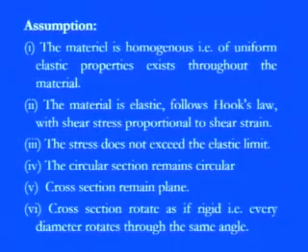So these two are the biggest assumptions: the material is homogeneous and is within the elastic deformation. Then there are more assumptions, like the stress must not exceed the elastic limit, because once it goes into plastic deformation, a permanent set of deformation exists in the material. Even if you release the load, the circular shaft has a permanent deformation, and if you apply more load, it will exhibit more and more distortion.